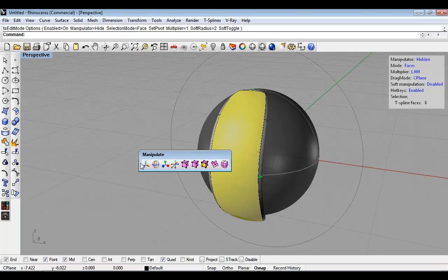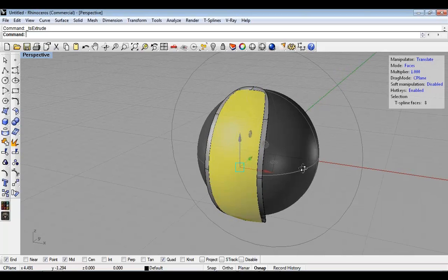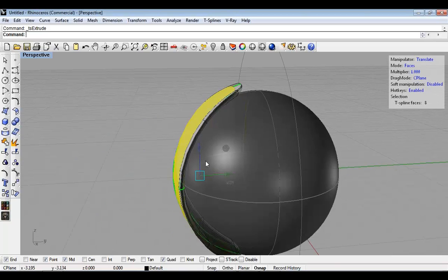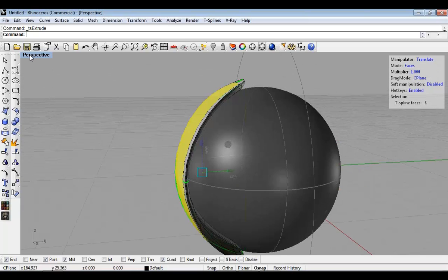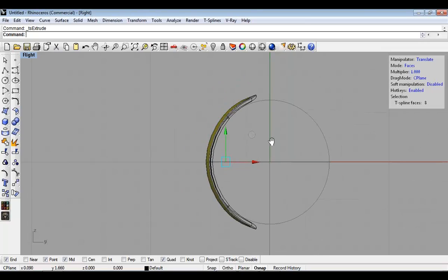So I'm just going to extrude this face twice in a row now, and the reason for that is at a later point when I come to hollow it, these two little edge sections close to each other are going to give me a nice hard corner without actually having a hard corner. I know that probably doesn't make too much sense now, but it will when I come to hollowing out the snake's head.